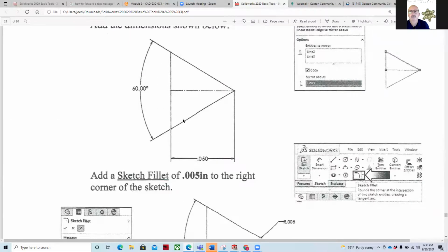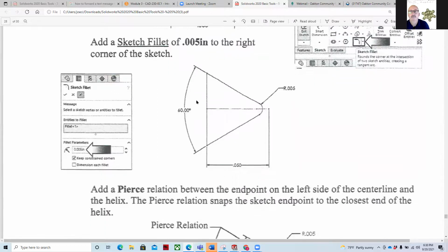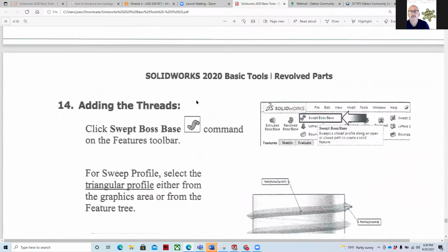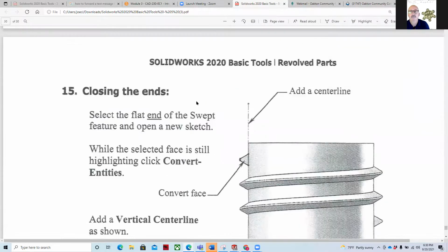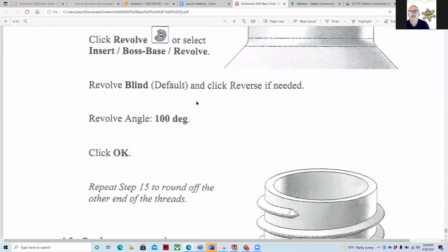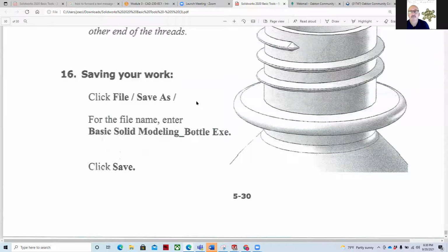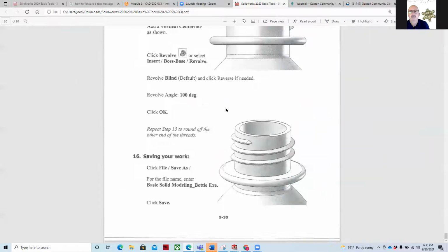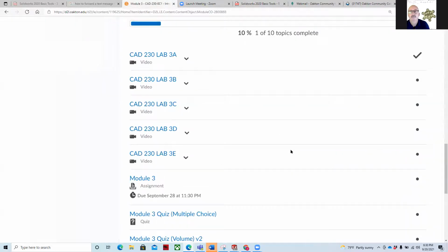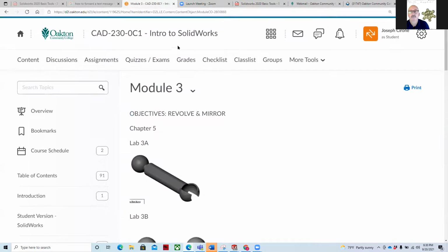And this is how tools are in the machine shop on a lathe. They'll have a 60-degree cutting bit that'll make the geometry for the thread. And you'll have to know what the pitch is and turn that into the feed and speed rate. But what's really nice about working this on CAD is that you can 3D print them with the threads and test it out. So that's the exercises for this week. Back to the main splash page.